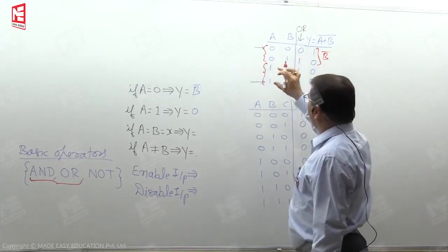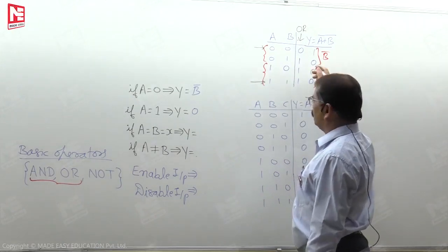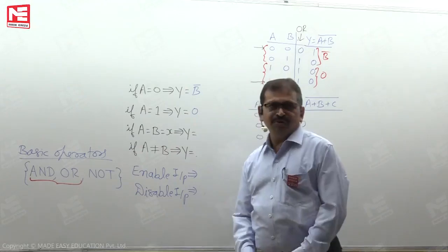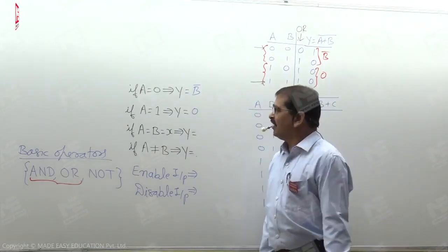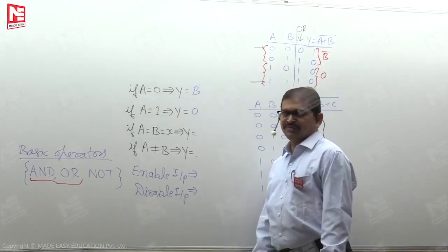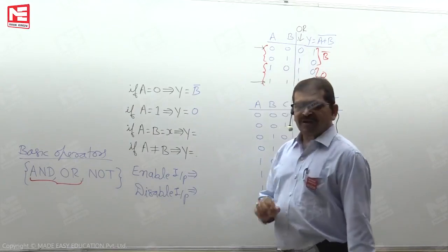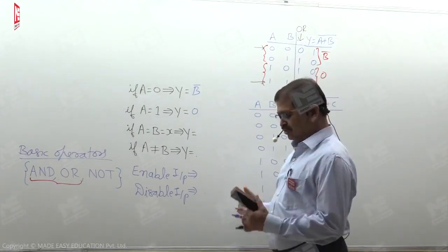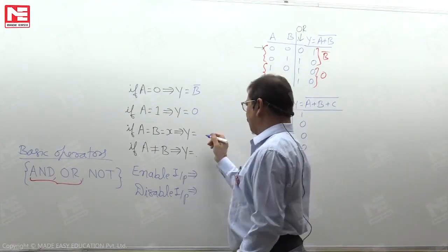Whenever one of the variables is 1, then B may be anything, and we are reading output as 0. So we are saying, if we want to use a 2-input NOR gate as a NOT gate, as an inverter, then one of the inputs must be connected to 0. Whenever both the inputs are connected to the same Boolean variable, as usual, looking at the first row and last row, it is possible to say it is the complement of the input.